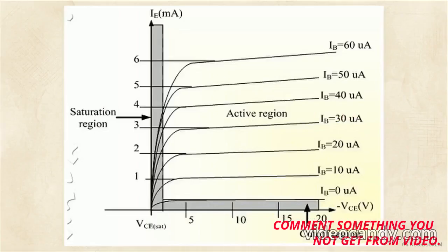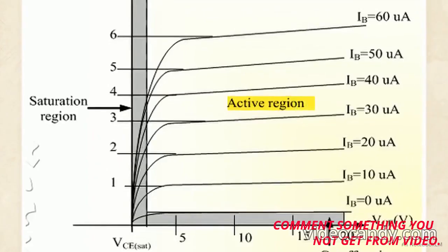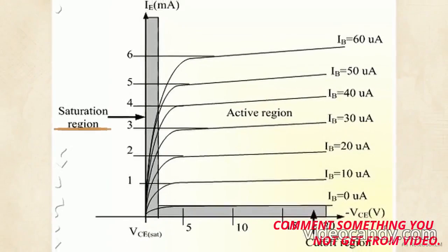This graph plots the collector-emitter voltage against the resulting emitter current. It provides the specific data needed to identify the component's operational boundaries under different loads. Most analog engineering takes place in the active region. This is the broad, flat plateau spanning the center of the graph, where the lines representing fixed base currents are parallel and evenly spaced. Here, the transistor acts as a linear, proportional amplifier.